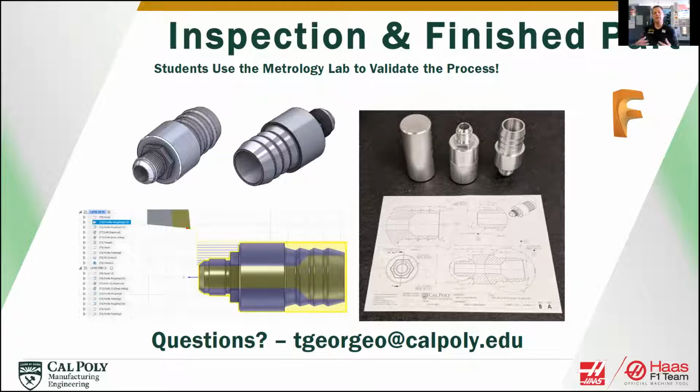Now, you can see the students go from solid model to finished part just from an engineering drawing. And at the end, they use the metrology lab to validate their process. So they measure the part using the optical comparator to validate that they machined that PEX fitting correctly.